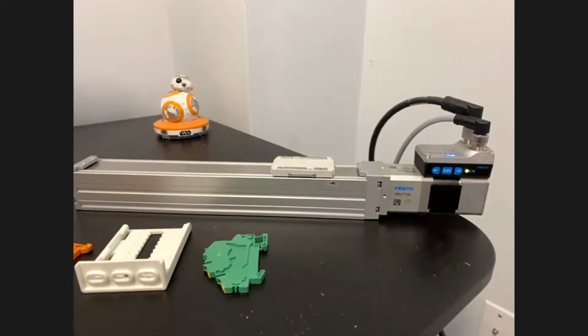And Alejandro, I know that you have not used this before, but there's a cool thing about this too. Think about when you use a pneumatic actuator. You have a pneumatic cylinder, and the only signals that you need from the PLC are just extend and retract. Just 2 signals, 2 bits. And usually on the pneumatic actuator, you have sensors mounted on the extend and retract, and you get 2 signals back.